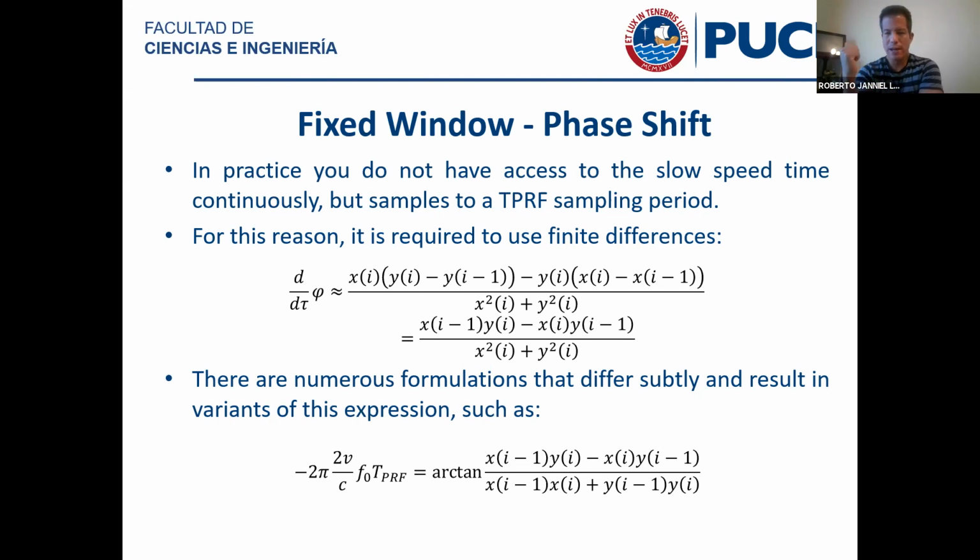There are many ways that you can work your way out of the phase shift problem. But in any formulation, it involves looking at the phase of the signal for 2 consecutive transmissions, seeing how much the phase shifted, and translating that into a time shift, which is translated into a distance, which is translated into a velocity, related one-to-one to the velocity that the particles are moving.